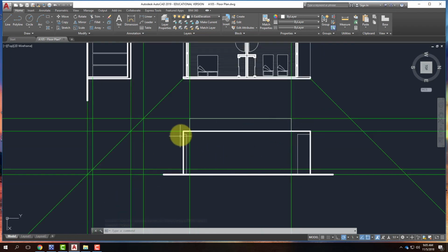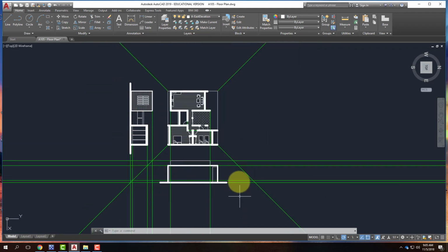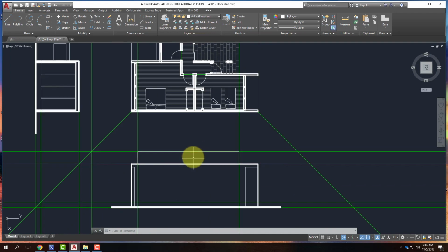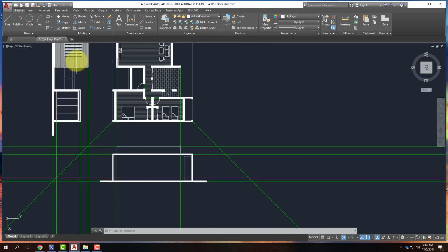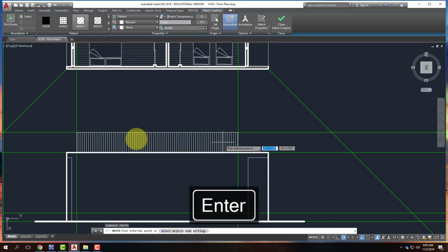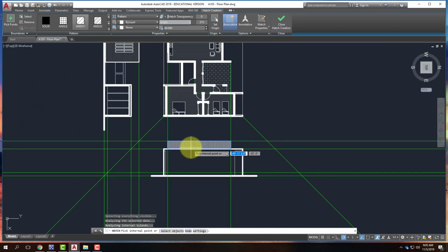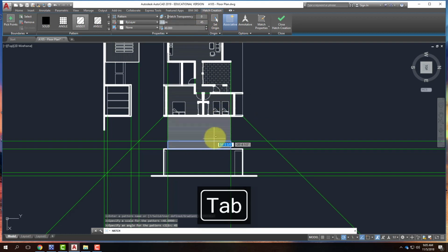The alcoves are both hidden lines, and they're nice and thin. So I've drawn this elevation. I should probably hatch this one back here to match that hatch because it was a different material. So I'll go back to hatch, and I'll pick it. In this particular one, it's going vertically. I wanted it to go horizontal, so I'd have to go back to 45 so that it was going horizontal.